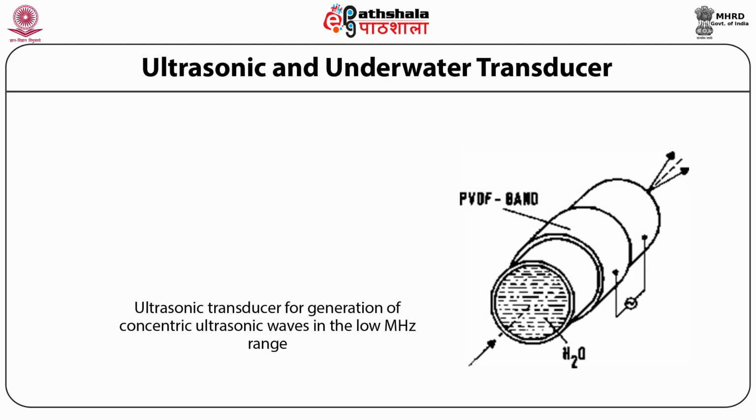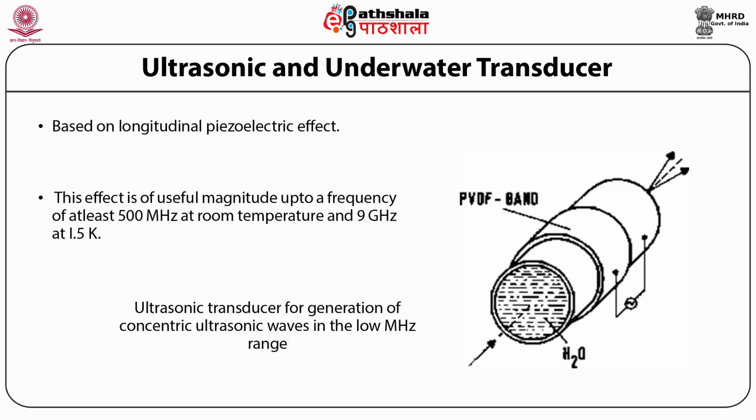Ultrasonic and underwater transducers. Ultrasonic and underwater applications of the piezoelectric materials are based on the longitudinal piezoelectric effect. The effect is of useful magnitude up to a frequency of at least 500 MHz at room temperature and 9 GHz at 1.5 Kelvin. There are several ways to generate and detect ultrasonic waves using piezoelectric materials, but of the most simple design are the bulk wave transducers.